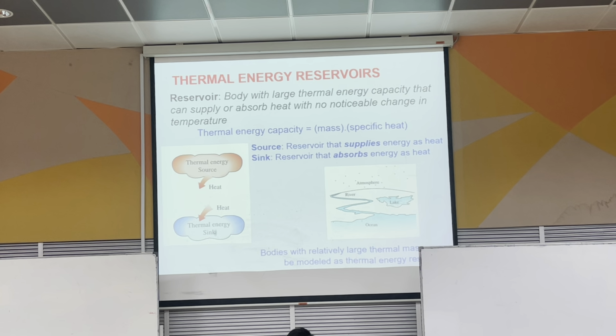Then after that it goes into the combustion chamber. In the combustion chamber it will mix with the fuel, they will burn, then you gain heat. So here is a Q-in process. Here this is a work-in process. Like I said, you will still need some energy to start it up. Then here temperature will further increase, but pressure actually won't.